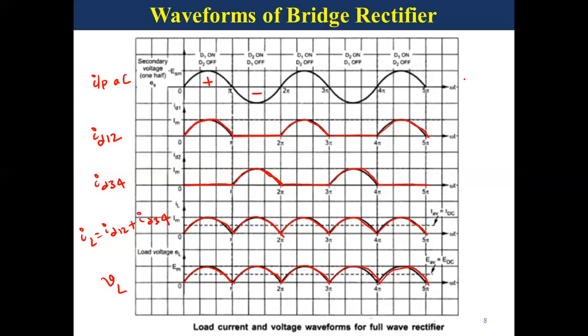Our input AC signal is bidirectional. So with this bridge rectifier, we are converting it into unidirectional. Still, our output consists of more AC component. That's why we can call this output a pulsating DC. It's not perfect DC, which is pulsating in nature.